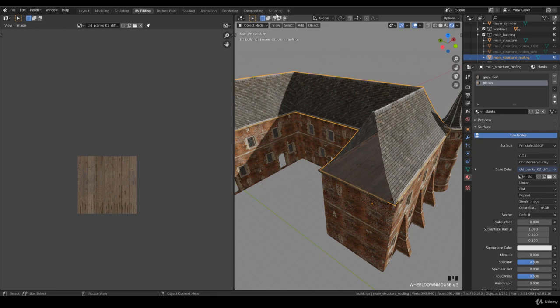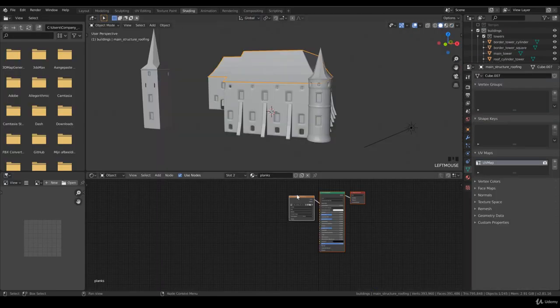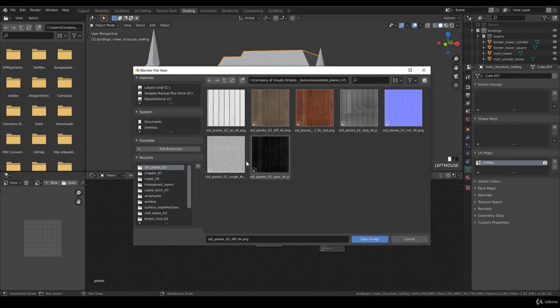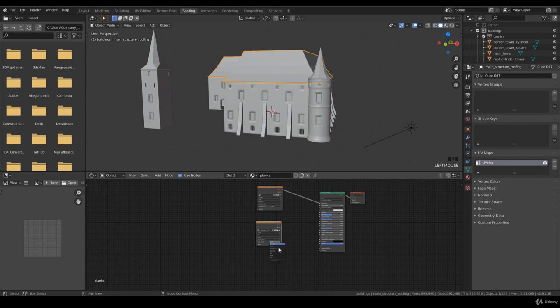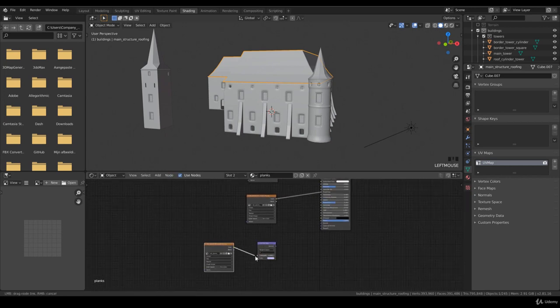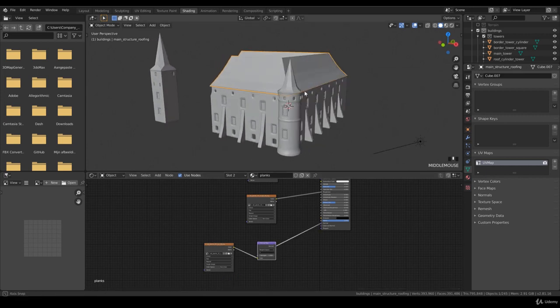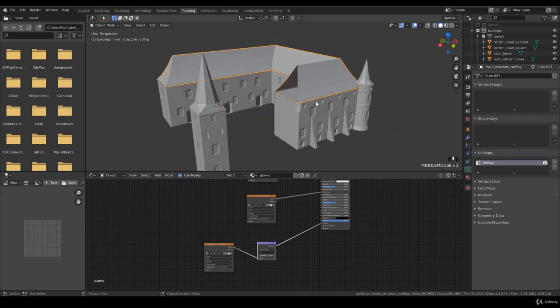So let's do some texture editing. We want to have the roughness and non-color data, and put it in the roughness, and we duplicate it, add vector normal map, and put the color into the color, and we want to select the normal map, non-color, and put this into the normal. Just perfect. So a quick view, render it.